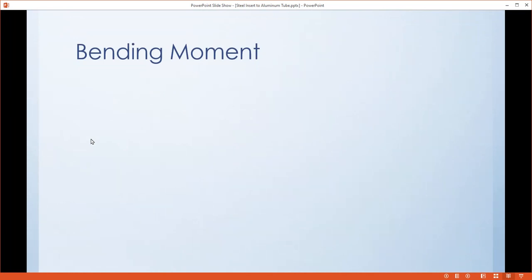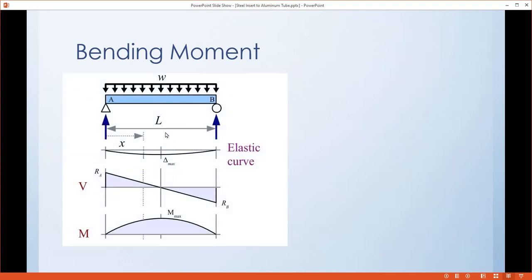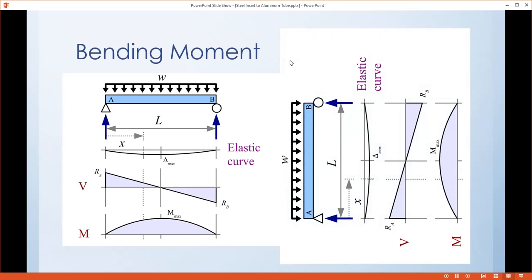Then, based on your rectangular shape, the moment of inertia changed. So it is going to improve the bending moment. Based on the standard simplified model, I just show you an example. This is a simplified unilateral wind load, and we just flip it over. Then we can simplify the moldings considering the wind load, and you get maximum deflection and maximum moment in the middle.